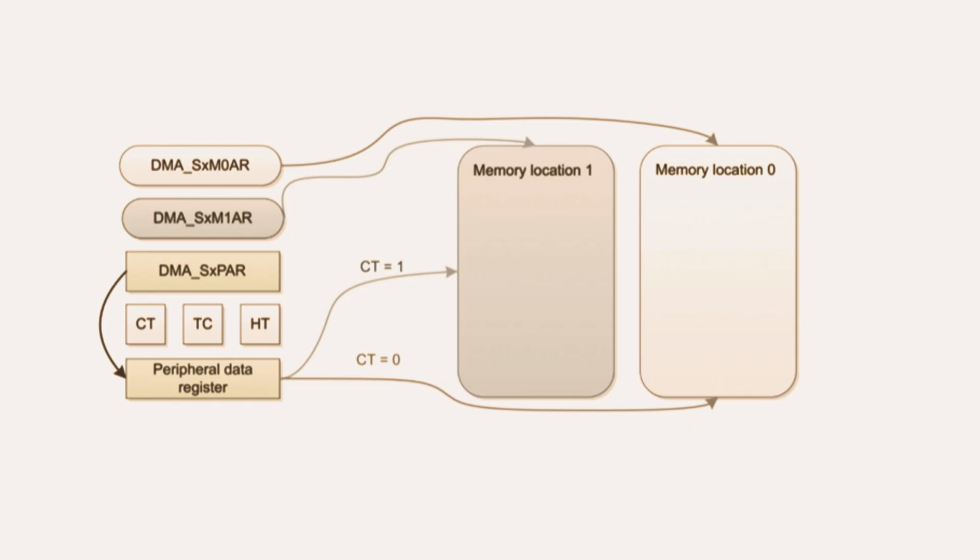Much, much less CPU overhead. That sounds incredibly efficient for precision measurements. It is. It's the perfect way to trade off that raw sample rate, because you're collecting many samples for one result, for significantly enhanced resolution and noise reduction, all while keeping the CPU load extremely low. What's the typical flow or setup for DMA-based oversampling?